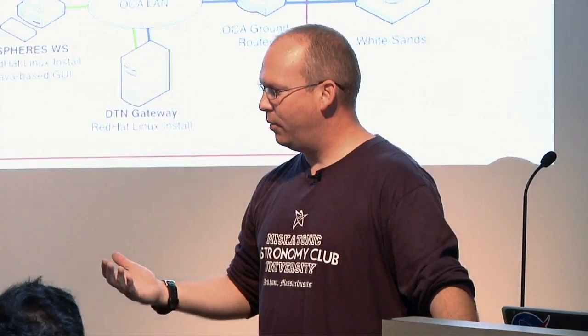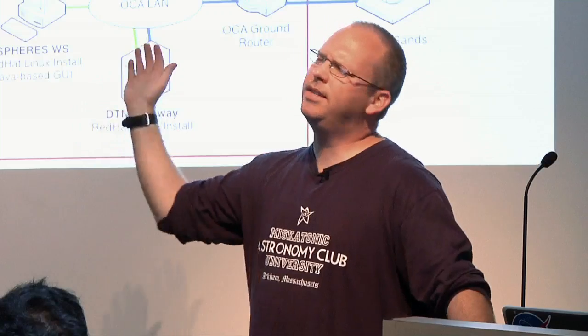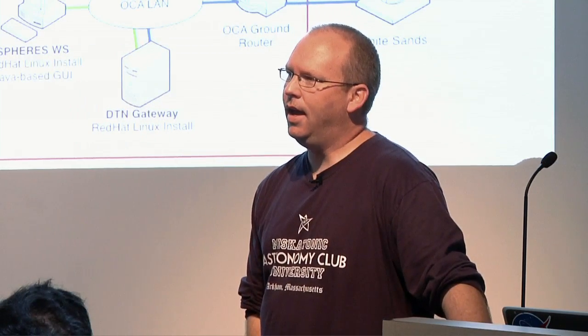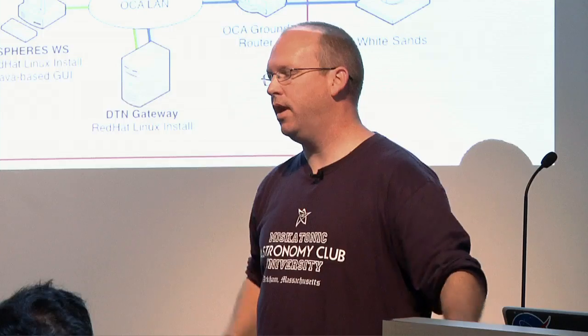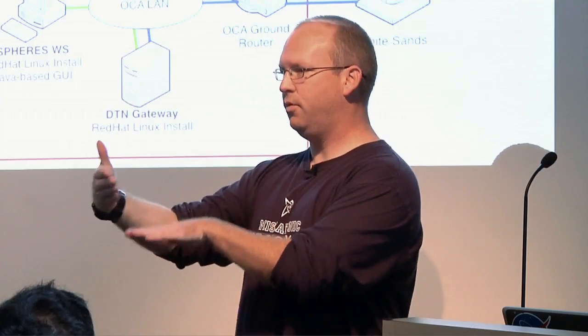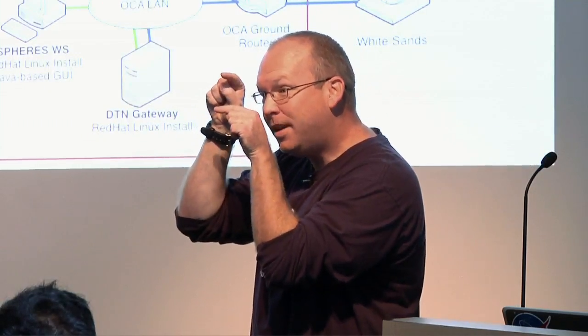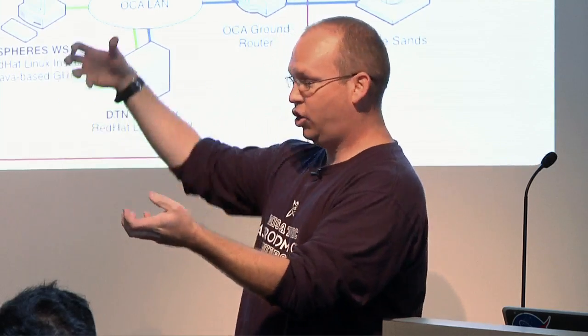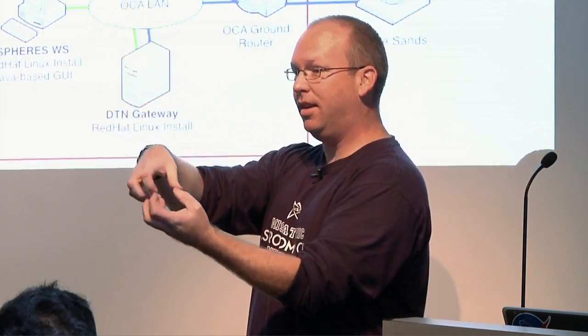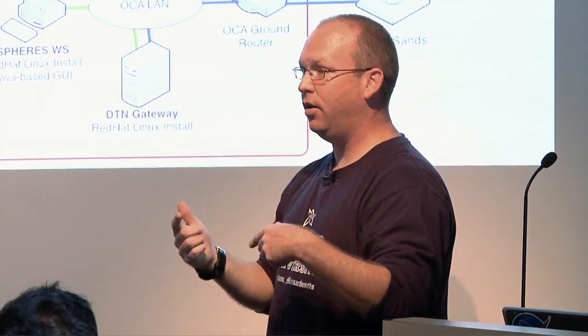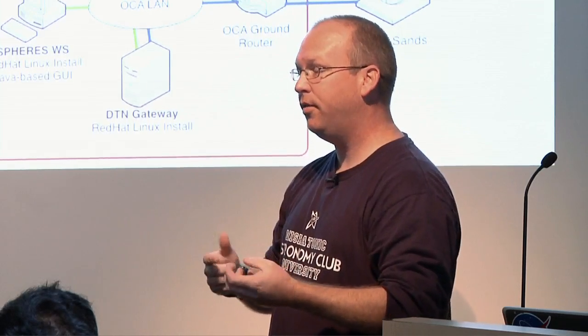We were told repeatedly, oh, well, it's in the next module, you'll be fine, the laptops use it all the time. And I kept having to remind the engineers, okay, your Lenovo T61 laptops have this huge antenna that wraps the screen. Our antenna is about this big, and we put a giant six-pack alkaline battery thing on the back of it. Depending on which way it's turned, we're attenuating that signal pretty significantly.